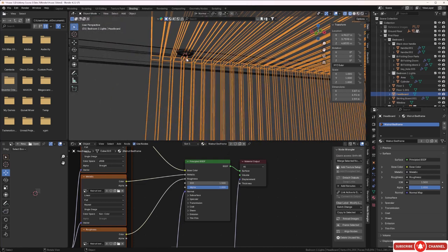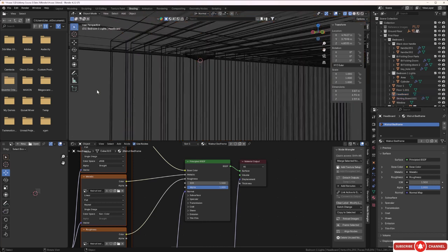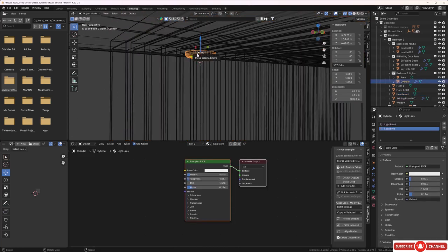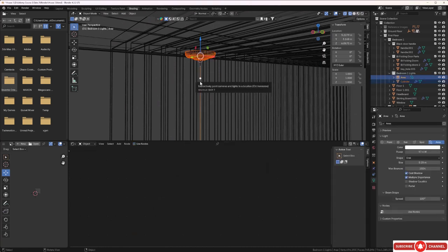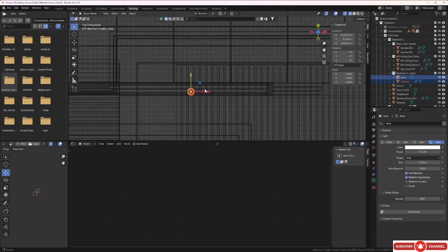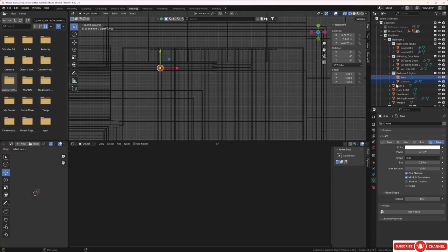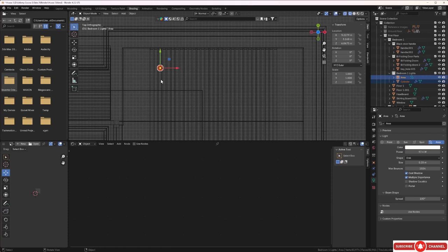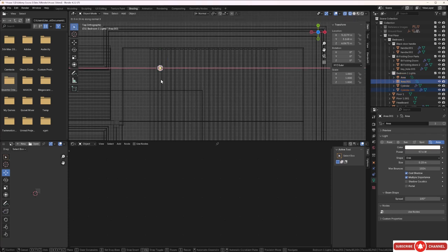And now let's deselect this and then grab the light and the light lens or the light bezel, and now let's hold shift and grab the light itself, and now let's press 7 and let's see this from the plan view, from the orthographic view. Let's turn off the ground floor so we can't see that because it was a little confusing. And now what shall we do? Let's press Alt D and X, and let's bring a copy across now to the opposite side, around about there, like that.